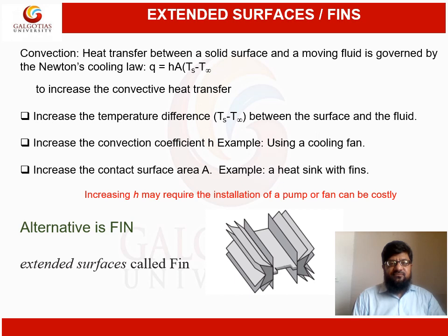Extended surface fins. We all know that the heat transfer by convection from a surface because of a moving fluid can be calculated by using Newton's cooling law. Q is equal to hA times the temperature difference. So to increase the convective heat transfer, we must increase the temperature difference between the surface and the fluid, that is Ts minus T infinity.